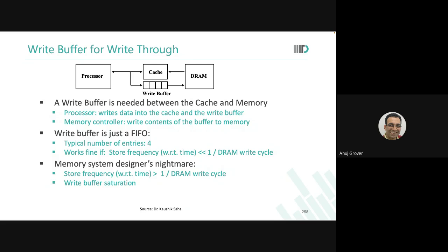And again, there is an optimization over here. This is just like when you have two particular blocks operating at different frequencies and you have to interface them, then you need to put a small buffer, two FIFOs, in between. How to size that? It's not a matter of just putting in some arbitrary size. It's again based on some assumptions that you will see based on what program you are running, what the architecture is, and all those things.